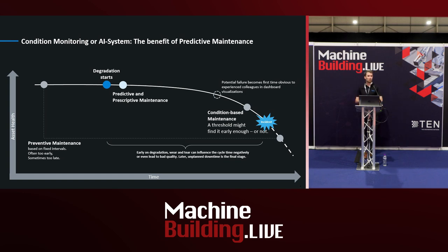And as everyone will know, this is a very, very common picture. That length of time depends on the application. We don't know how long that will take as the asset health slowly degrades over time. And at some point, we'll have an incident. We don't know what that incident is, but let's take a pneumatic cylinder. It's leaking on the front nose cap. It's got a defined leak rate. It may be the leak rate exceeds a permissible value and the cylinder stops working within its functionality.